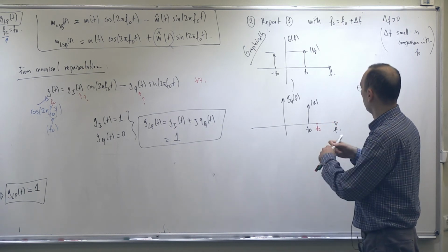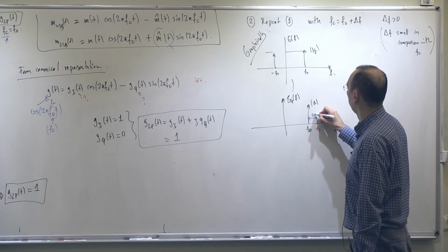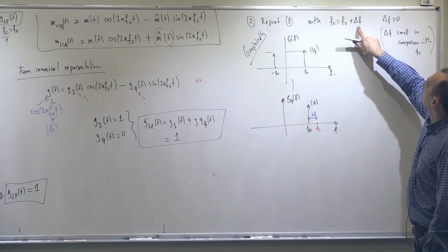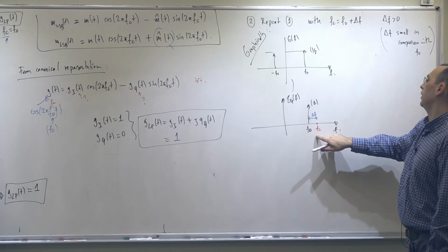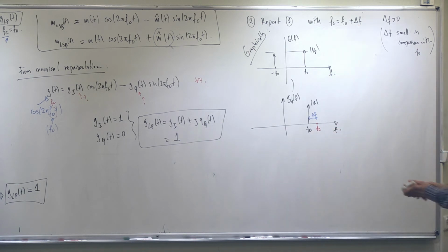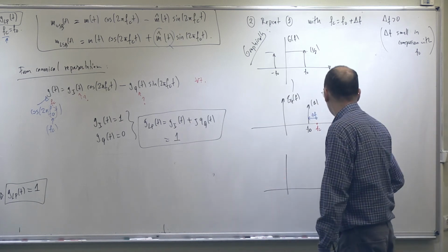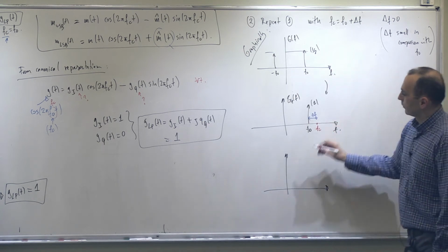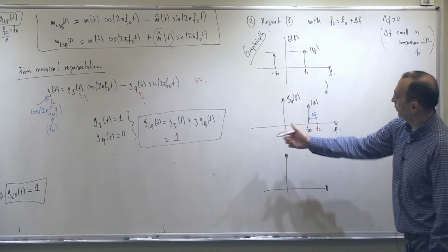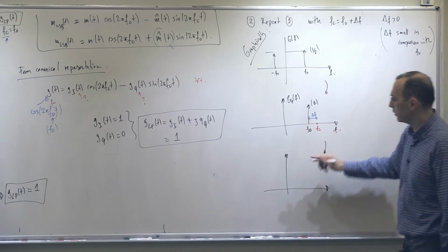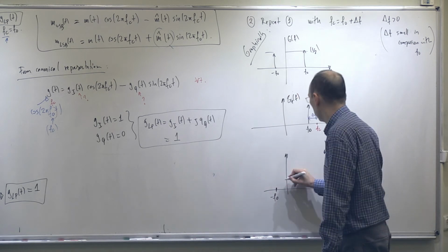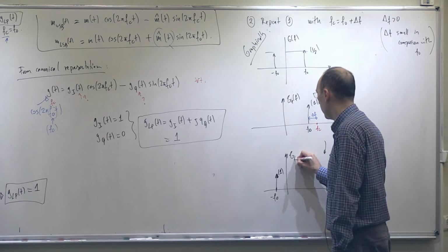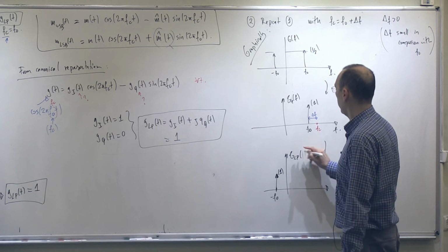Meaning that there is delta F hertz in between. So Fc is this value plus, maybe if this is like 1 hertz, F naught plus 1 is equal to Fc. Now, if I shift to the DC frequency by the Fc amount, what do I get? So I get minus delta F, and this is equal to 1. Am I right? So this will be our low pass equivalent in frequency domain.